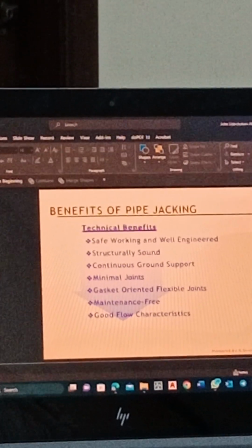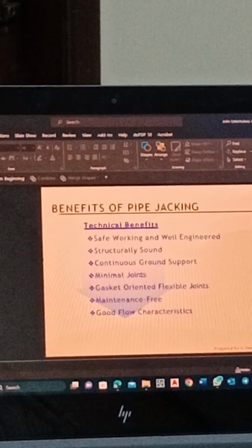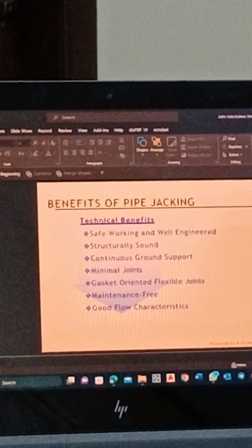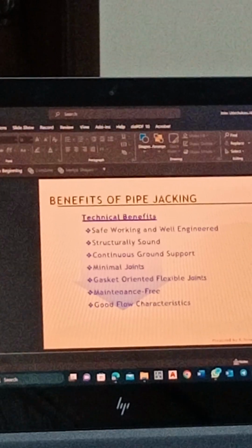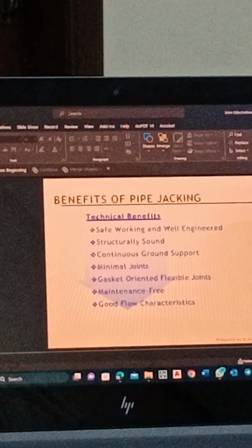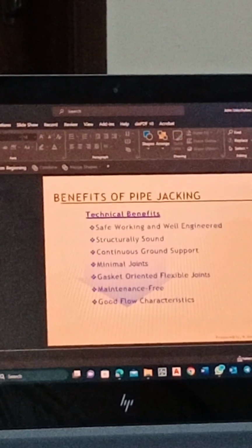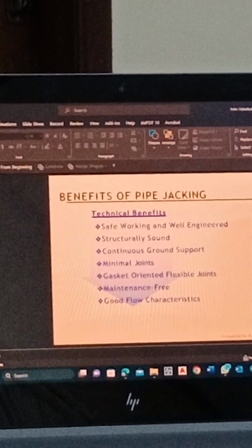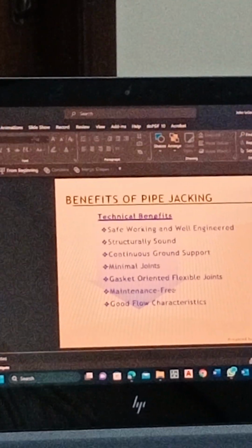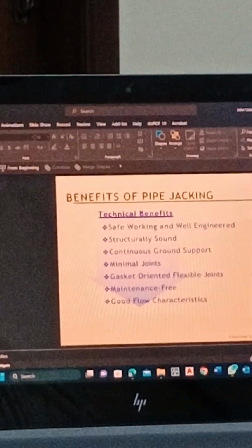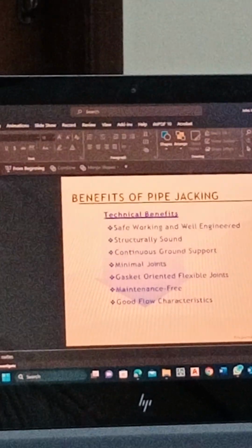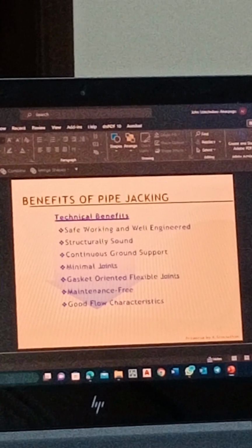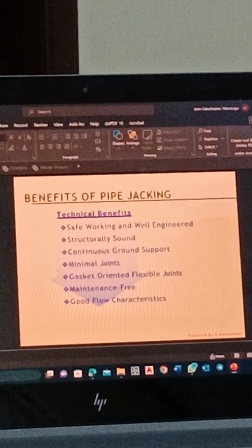It's just working. But for the surface drain, you must desilt from time to time because of sand and all these, so the maintenance is higher and more frequent. This one, the maintenance is so low. Let me tell you why. Sometimes water and sand will mix up and come, but because of the pressure of the water, it will push both the sand and the water at once. The water has some pressure, so no matter what it carries, even stone, it pushes it through. Where it may have some maintenance is maybe at the outflow, where the river is. So we may have to desilt the river from time to time. But for the inside, it looks very smooth.